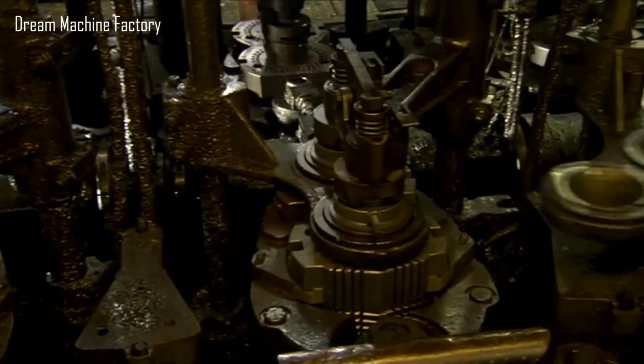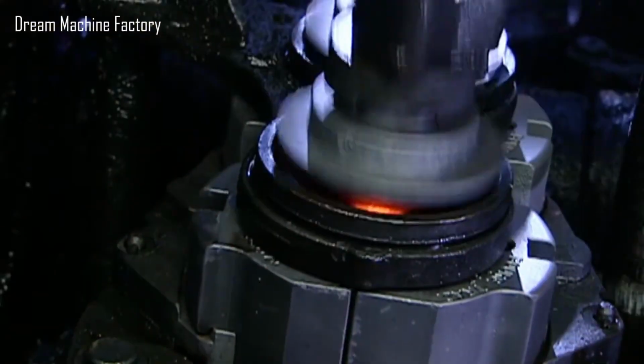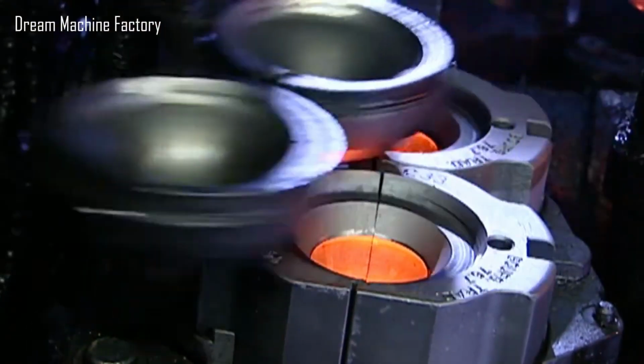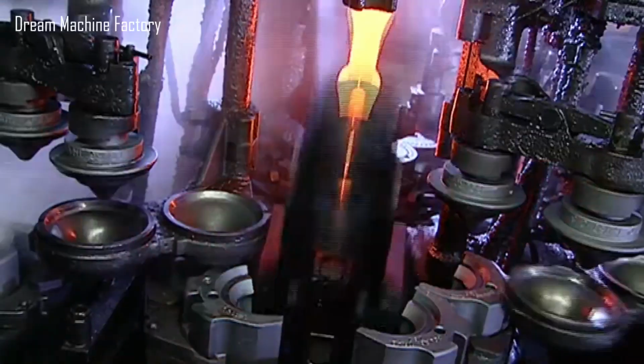glass. From the furnace, molten glass flows through narrow channels called feeders. It passes through an opening at the bottom, where it is cut into equal portions called gobs. These gobs are delivered to blank molds in an individual section forming machine.